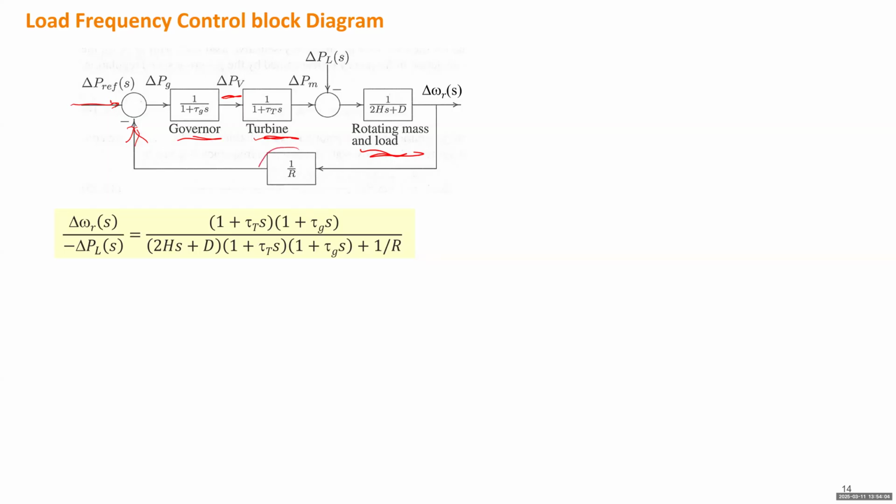This is the major part of the load frequency control. That will close this loop and make it a negative feedback, so it will form a droop control. The R here indicates the slope of the droop control. The smaller R means you have better control, because this feedback signal will be multiplied by 1 over R. So if you take a very small R, oh, sorry, I didn't distribute the slides. Yeah, but we haven't gone to the new slides yet.